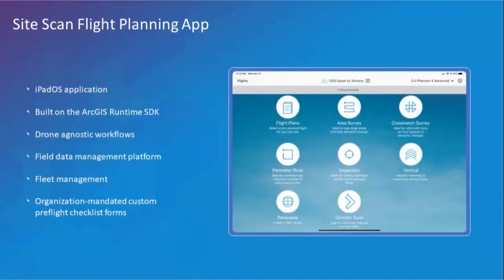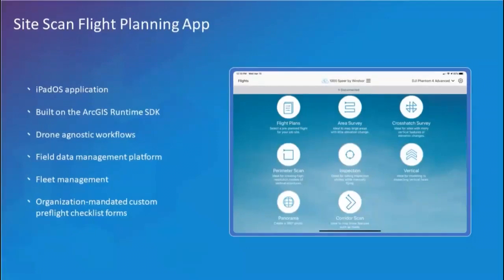Yes, so this kind of relates to the ground control point question that we had earlier. So the data that's collected straight from the drone is going to be accurate within 3 to 6 feet, 1 to 2 meters. But in order to get more accurate data, you really need to apply survey control or ground control to the data so that the resulting data points from the ortho and the point cloud and the digital elevation model are as accurate as possible.